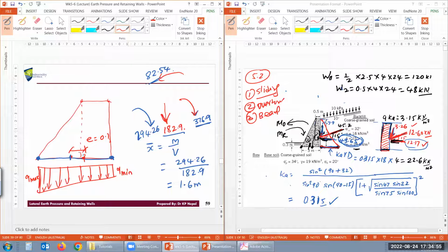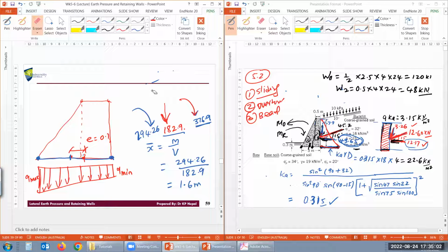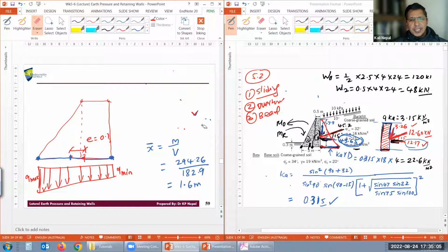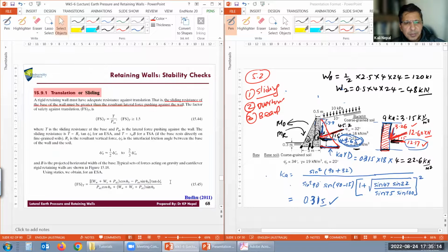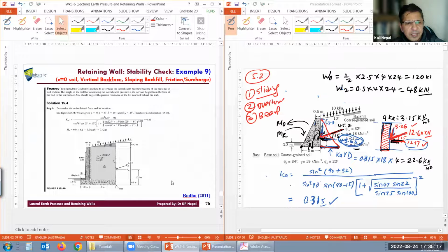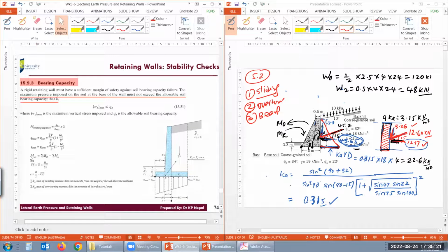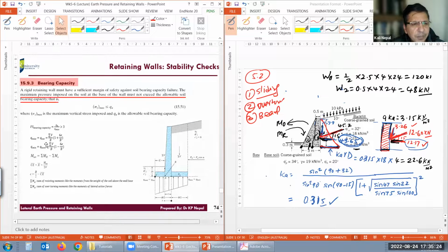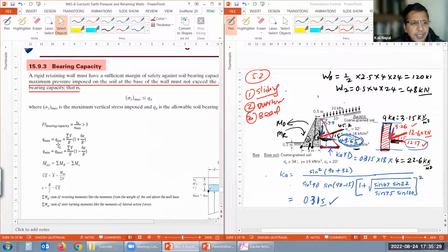All right, so how much would it be? There you can directly use the formulas, right? Can I go there now? Yes. You see the formula, because we know the eccentricity of loading, so you can calculate directly what Q max and Q min are based on this diagram. Where is the Q? Oh, that should be somewhere there. You see the sum of all vertical forces. Can you write this Q max and Q minimum formula, please, guys?